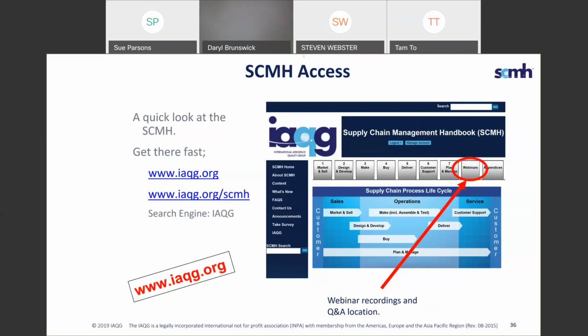Right. You don't want to do all this stuff at the last minute. No, you don't. You don't want to write the book at the end. If you look on these documents, there's always three blocks: prototype, pre-production, and production. So prototype is early on. Pre-production is when I'm just getting ready to make my, if you will, my FAIR run. And then production says, now I've used my information from my FAIR run and I've used other information and I'm ready to document this. This is what I'm going to live with as a document. So there is certainly a maturity path there.